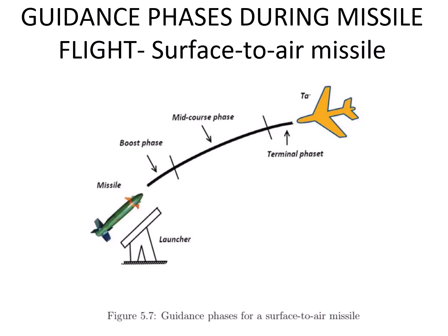The same thing happens with surface-to-air missiles, where our first maneuver is the boost phase or launch phase, the second is the mid-course phase, and the third is the terminal phase. In the boost phase or launch phase, our objective is to clear the launcher and achieve the velocity and altitude, irrespective of the location of the target. So here we don't need to employ guidance systems.